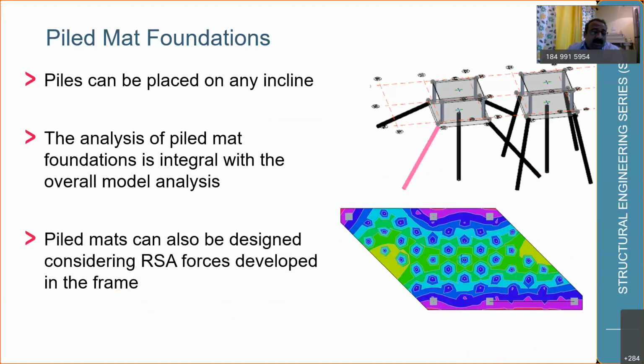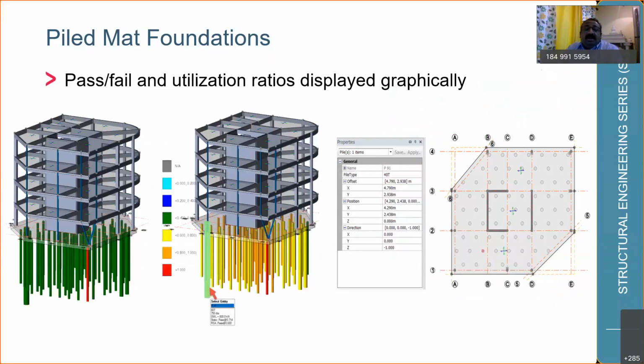The foundation is integral with the overall model analysis, and the pile mat can also be designed considering the RSA forces developed in the frame. That is also possible, even with inclined piles. And it generates the pass or fail information, with the utilization ratio displayed graphically.